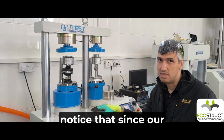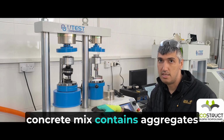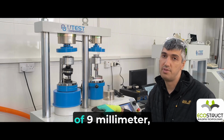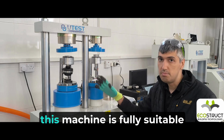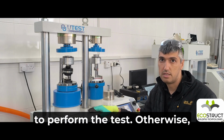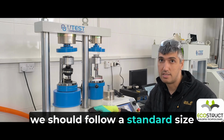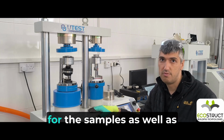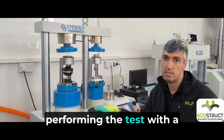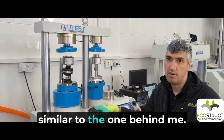Notice that since our concrete mix contains aggregates with a maximum size of 9 mm, this machine is fully suitable to perform the test. Otherwise, we should follow a standard size for the samples as well as performing the test with a machine with more capacity, similar to the one behind me.